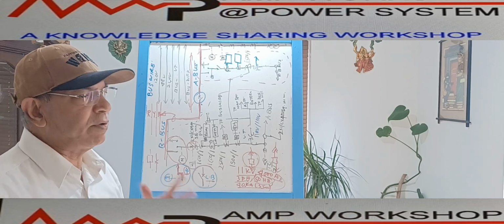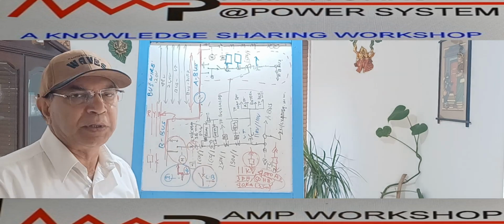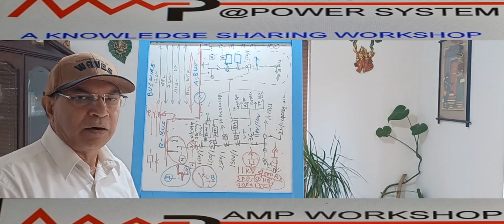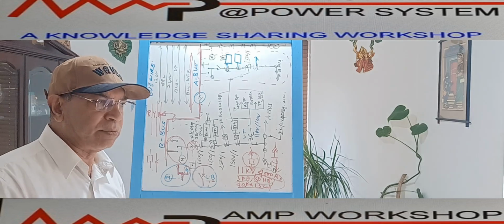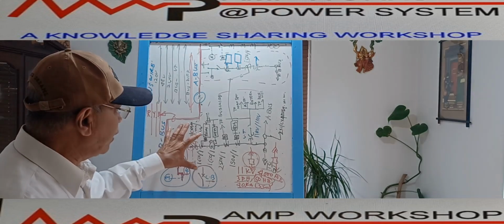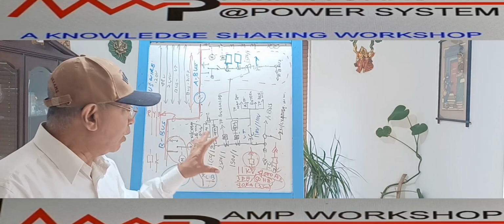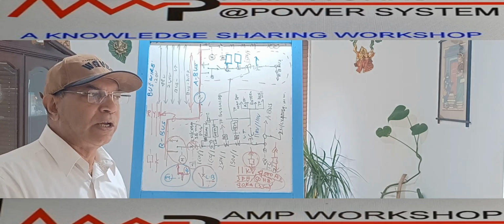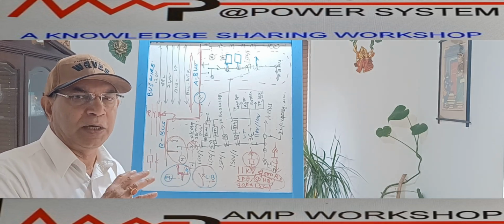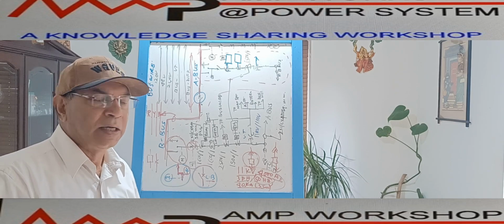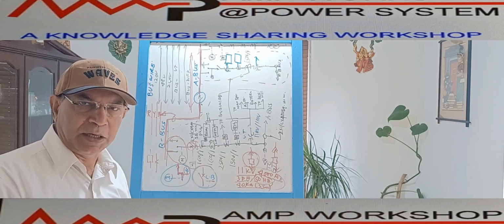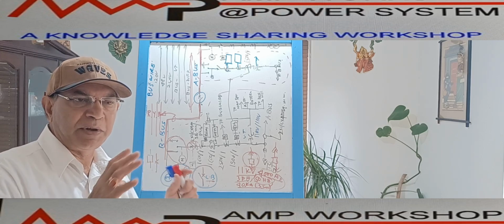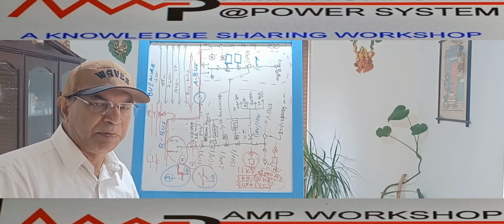Now first we have to identify how many CTs will be there. In the case of generators, for this rating of 20 MVA, we have one relay which will include all the protection functions of the generator. Then there will be a multifunction meter, which will monitor various parameters of the feeder.